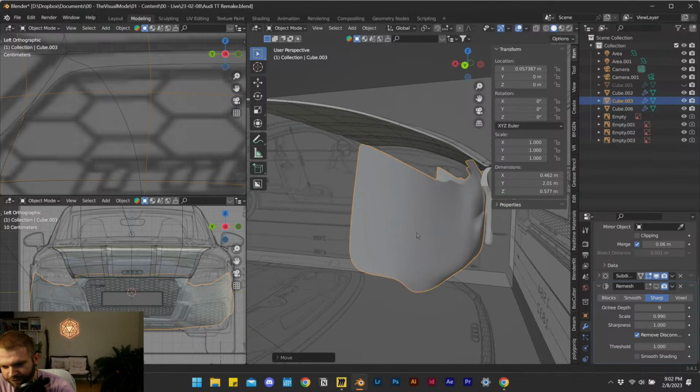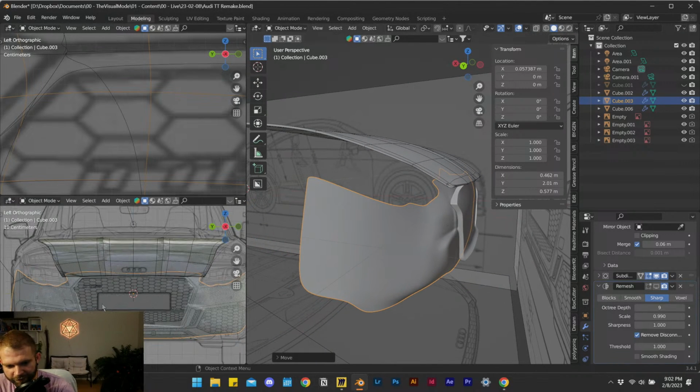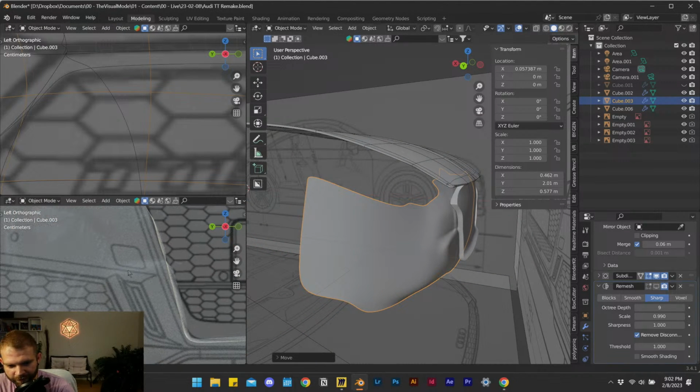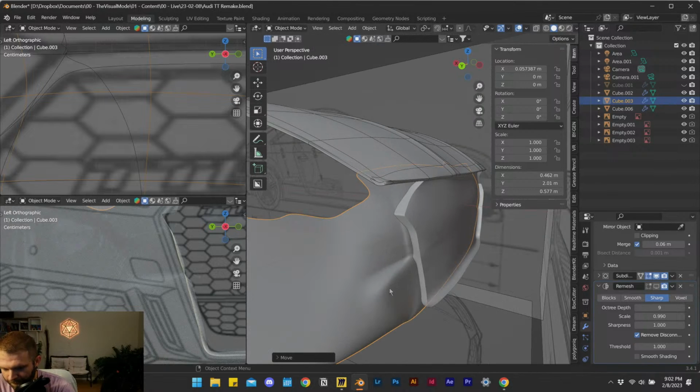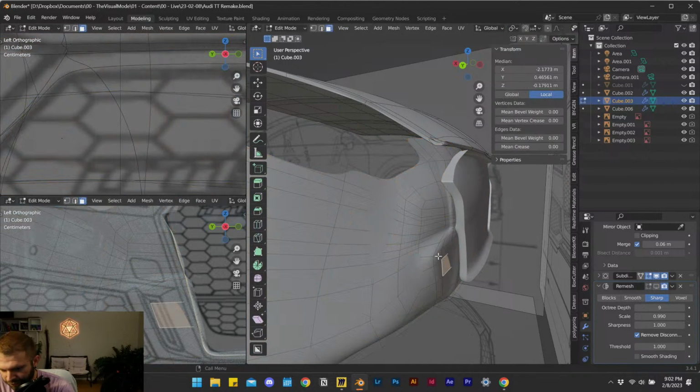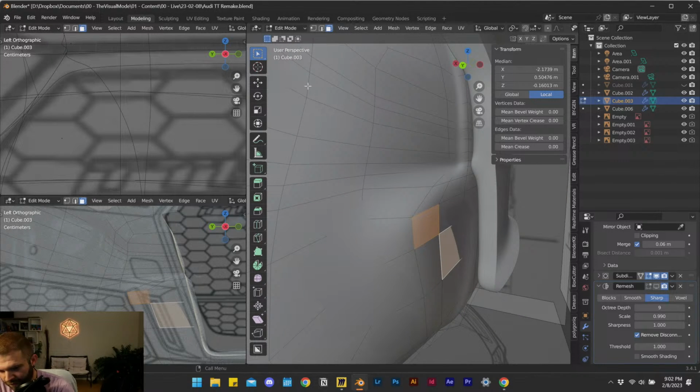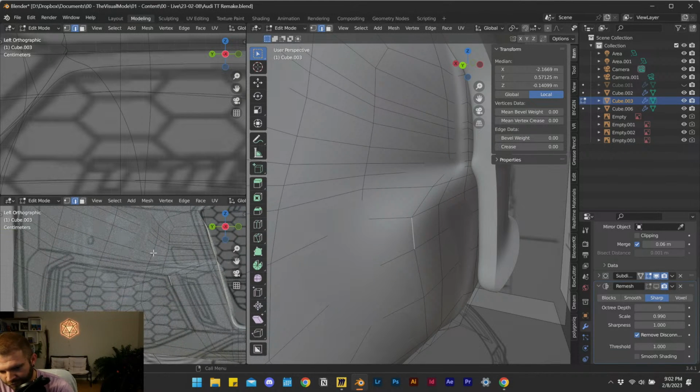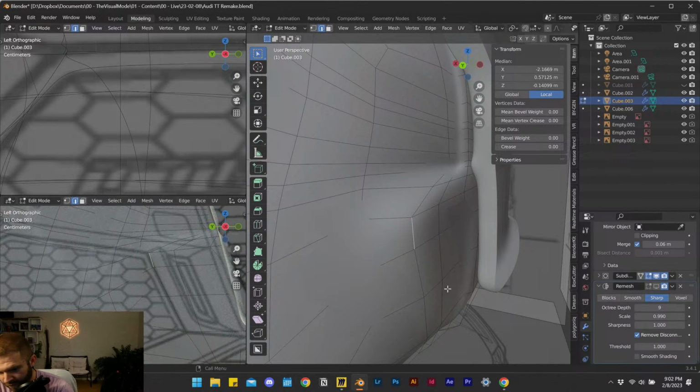And possibly even just start continuing to build like this over and over to get this concept shape out. This pinch is actually working really good in my favor to build out that face. If you wanted to, let's say, add a lip out here, if I weren't going to extrude this whole face out, or if I wanted to make this edge on the body a bit sharper, I mean, we already went through the mean crease over here, so that becomes a sharper edge for the car.